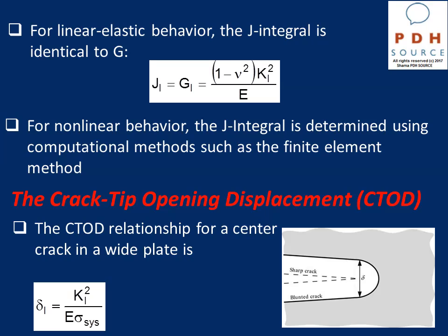Similarly, we can define the crack tip opening displacement, CTOD. Actually in 1961, Professor Wells of Queen's University in Ireland proposed this parameter, which is the opening at the crack tip, to be a measure of fracture toughness. This parameter is basically known today as CTOD.